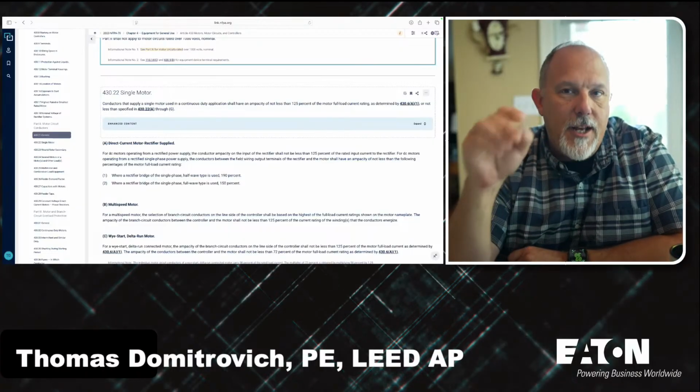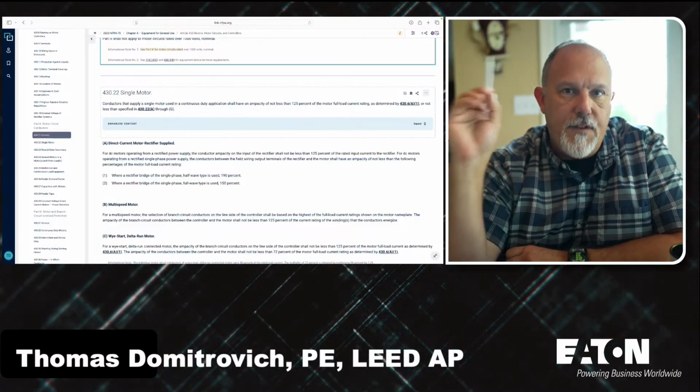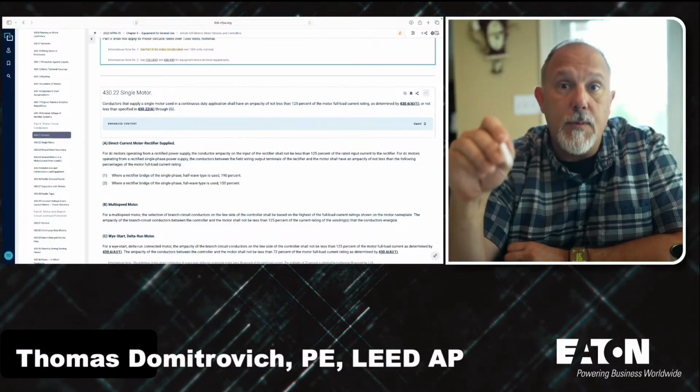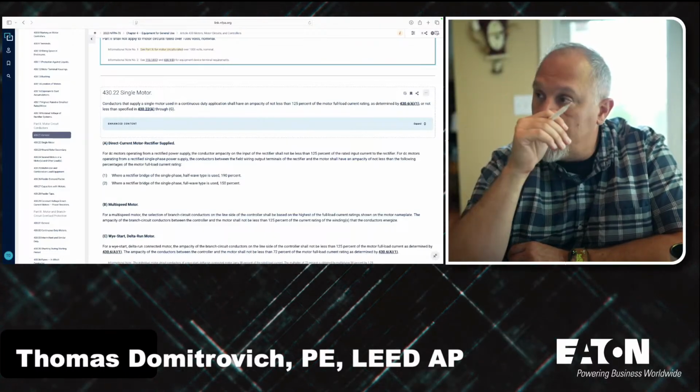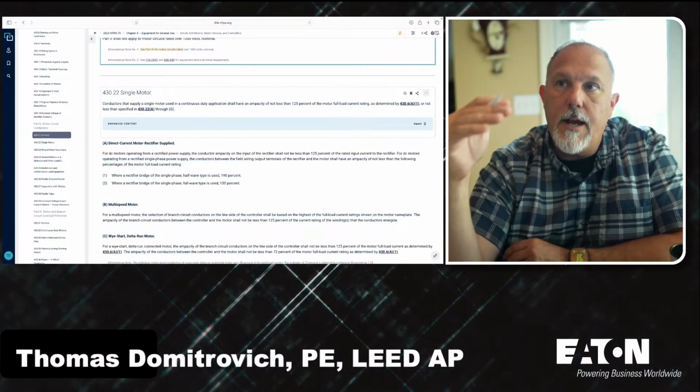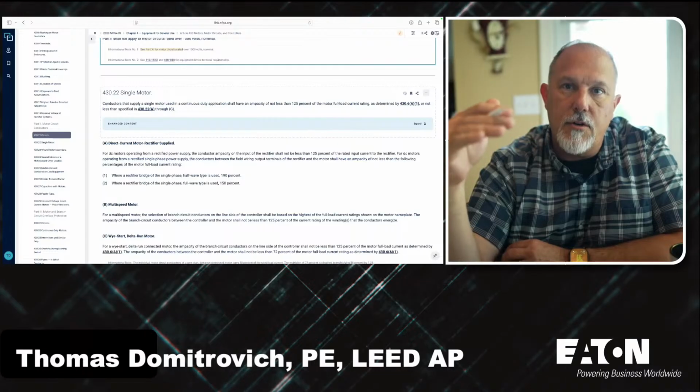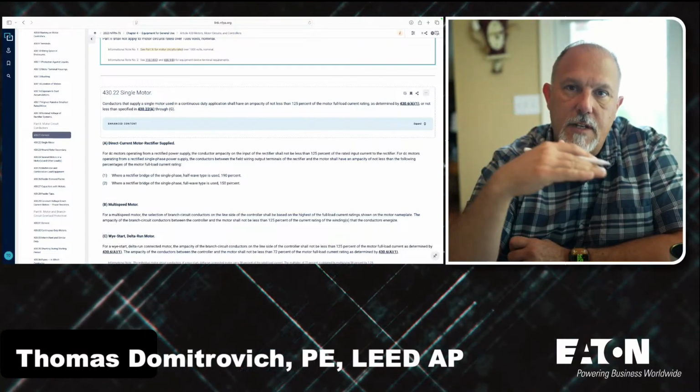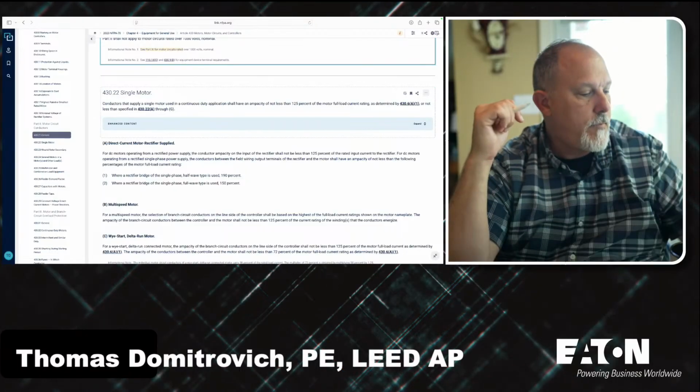Now remember, check out the IAEI News Live video that I did this week, Tuesday. We talked about continuous current, and for motors I don't have a continuous current, because they don't meet the definition of continuous current. Go check that video out. A motor has what we call continuous duty, so that's a motor that is designed to operate continuously. So we're going to size our circuit for this continuous duty motor.